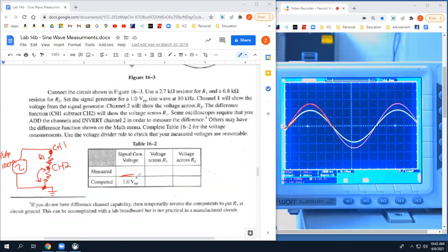So I'm putting that voltage on the entire circuit, just through the 2 resistors. Okay. Channel 1 is reading the same thing as the function generator, outside to outside. Channel 2 is measuring voltage across the resistor. Okay. So all the grounds and the commons are together on this side. Then you've got function generator in channel 1 here, positive, channel 2 positive right there.